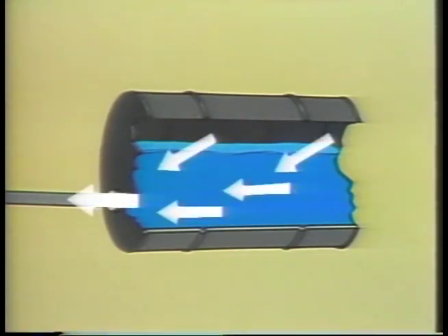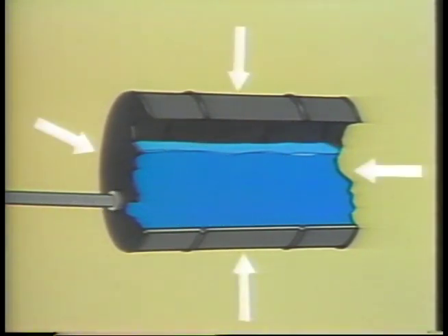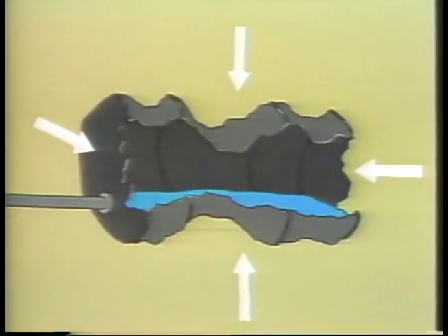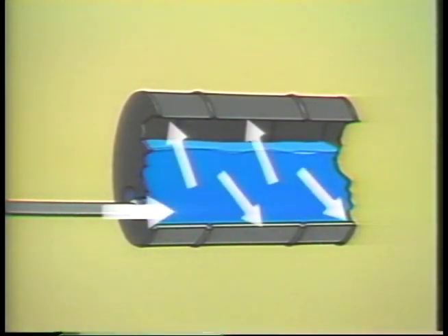But if we seal the opening of the drum and begin drawing fluid out of it, the pressure decreases inside. The greater force of atmospheric pressure on the outside of the drum causes it to collapse. Well, let's return the drum to its normal configuration and consider what would happen if we force air into it. Eventually, the pressure in the drum gets high enough to rupture it.